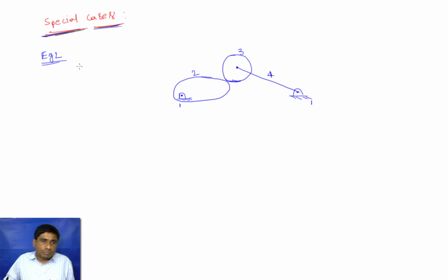This is another example. Here we have a cam set. This is the cam, and this is the circular disc, even though it's a little bit deformed. This cam is pinned to the ground link 1 with a revolute joint, and this disc is again connected to a link, and that link is pinned to ground using a revolute joint. And we have already seen that a cam pair has 2 degrees of freedom.